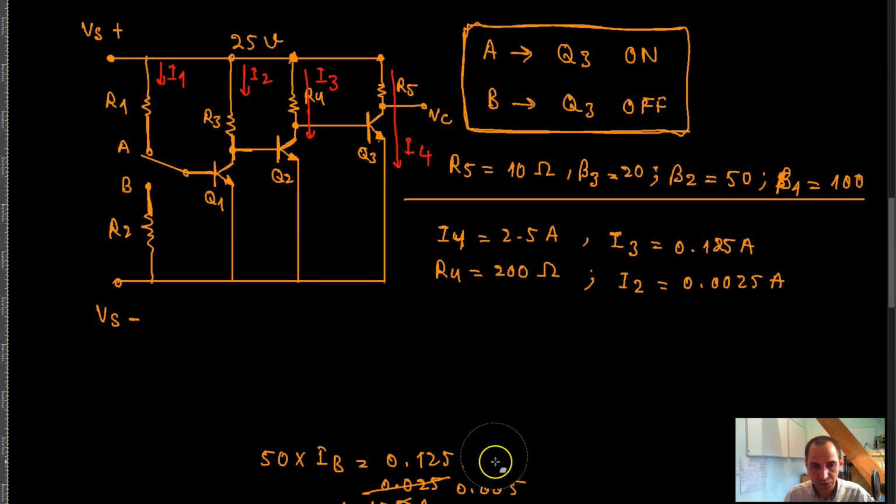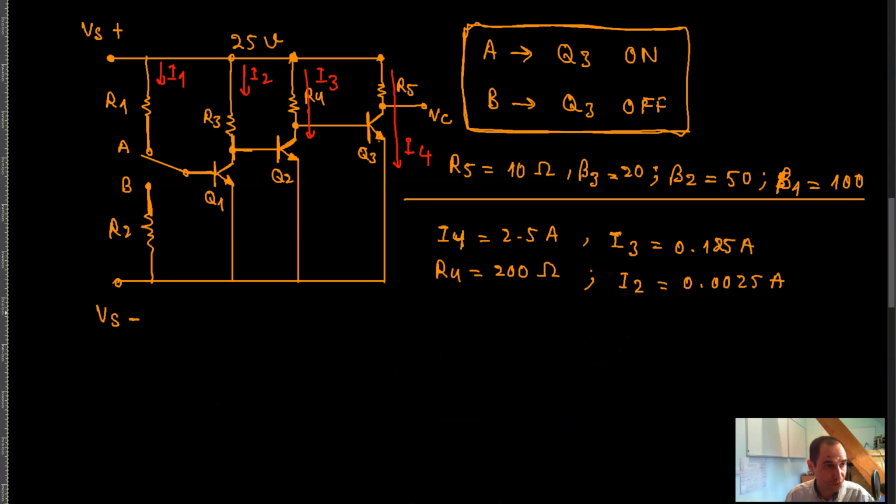we need the right resistor for that sort of current. So I of 2 is going through this resistor R3. If I write V is equal to IR applied to R3, I get again the same story. The voltage 25 volts of supply comes through R3, through the PN junction to the ground, ignoring the voltage drop here.